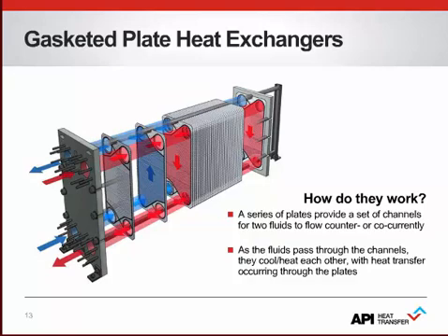The plates between the fluids are corrugated to increase turbulences of the fluids and therefore increase the heat transfer. Turbulences give pressure drop as well as heat transfer. So just a small example, cooling a hot tea in your cup. If you use a turning spoon, it is more efficient than if the cup is just standing still. This is because the turbulences increase the heat transfer.